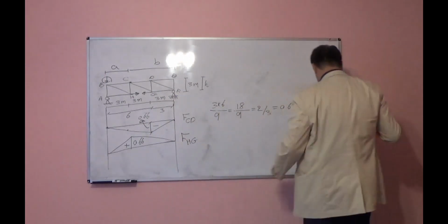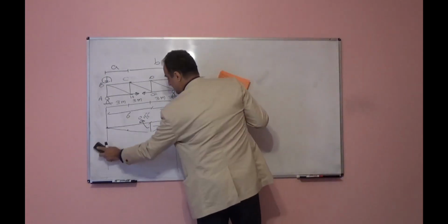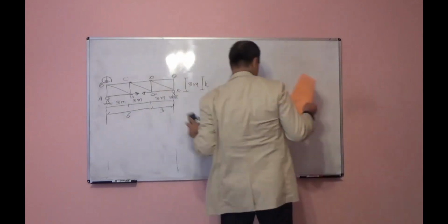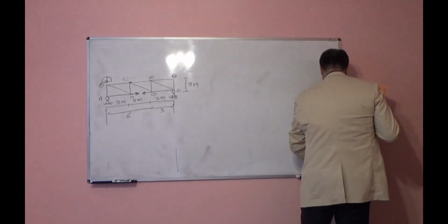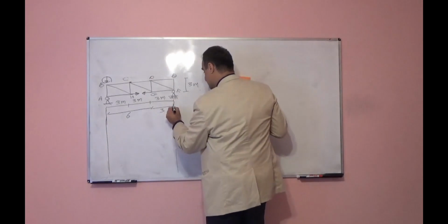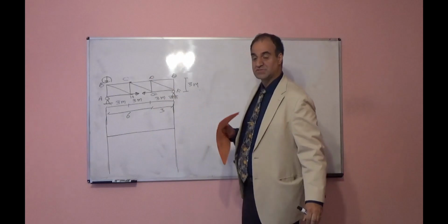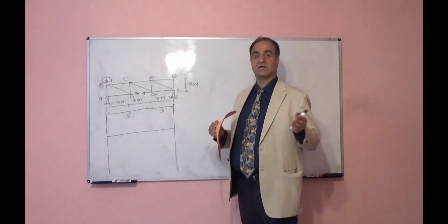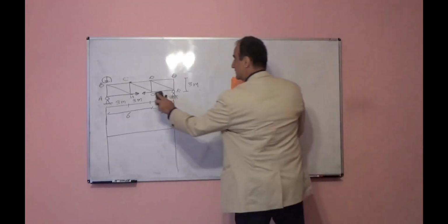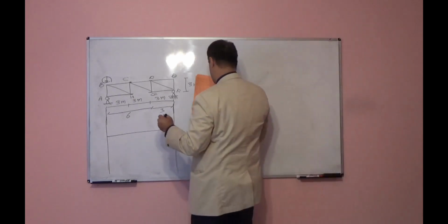Okay. Let's look at two other members. My recommendation for truss: always move the traveling load to different joints and find axial force. Then using Muller-Breslau, double check. That is better. But now we want to draw the influence line for member